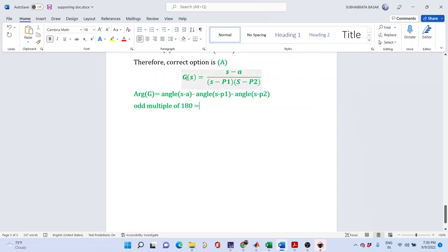So if a point is lying on the root locus of G(s), with the asymptote, when k tends to infinity, the poles of the system would follow that line. So that line is a part of the root locus.